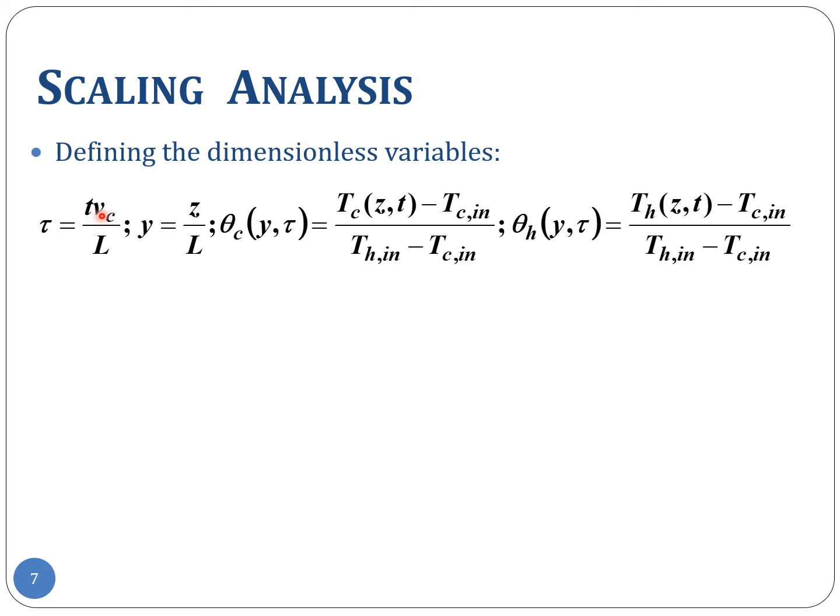But for the time being, choosing the phenomenon of bulk flow of the fluid as the characteristic phenomenon, what we have done is define the characteristic time associated with it. Now, the characteristic time is typically defined as characteristic length by characteristic velocity. Length by velocity will give a time. Volume by volumetric flow rate will give a time. So there are ways to obtain time.